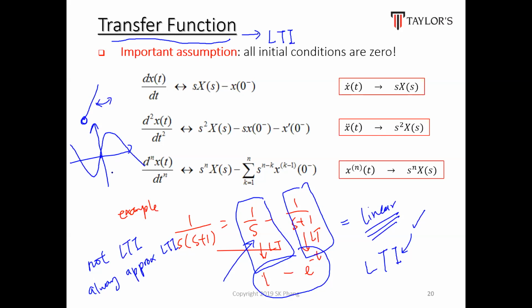But what engineers like to do is draw an approximation line. If you look at this approximation line and the blue original line, you notice that they look alike in this region, which they call the linear region. So they approximate this non-linear pendulum system as a linear system, and then apply the Laplace transform to find out the performance of the system.